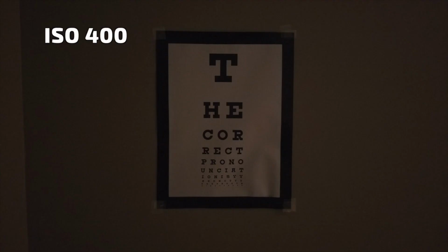But as we decrease from 800 to 400, and to 200 and to 100 and eventually 50, you see that by the time we get down to the bottom, there's very little contrast left between the letters and the background color. And this would be analogous to having an A-scan signal on your screen, which is so close to the noise that you can't really tell if there's anything there at all.